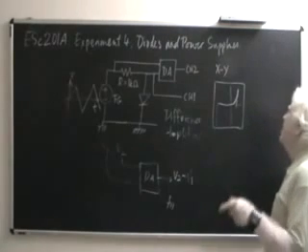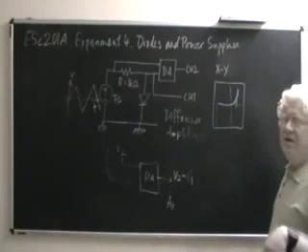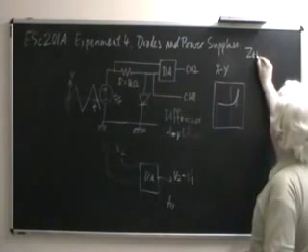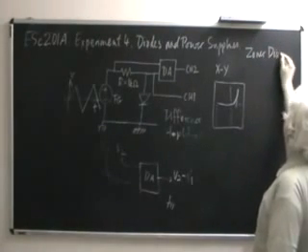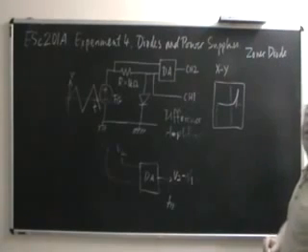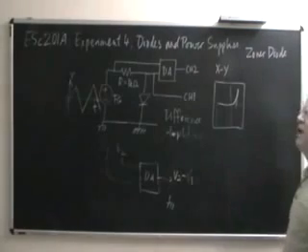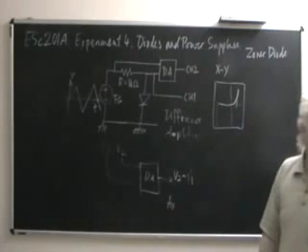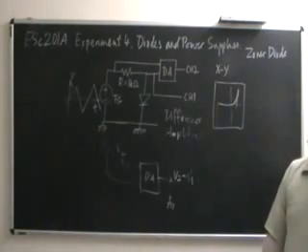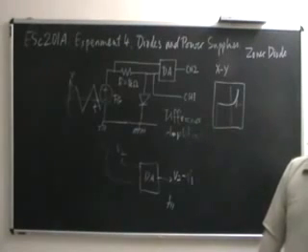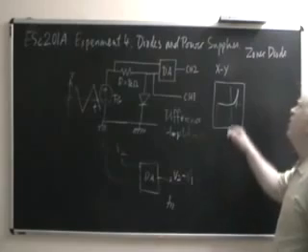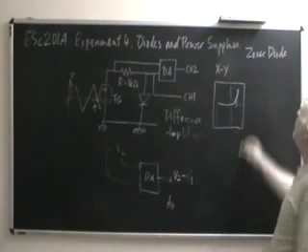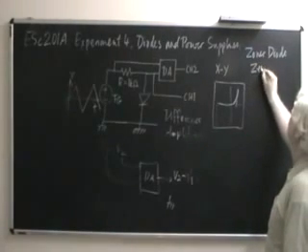Now, having done all this for an ordinary diode, we use the same setup to observe what is called a Zener diode. A Zener diode, as far as its normal diode characteristics are concerned, that is the forward behavior and a major part of the reverse behavior, is just like an ordinary diode. There is not much difference. Where it differs, however, is that it allows for a non-destructive breakdown under large inverse voltages. And that breakdown phenomenon is called a Zener breakdown.